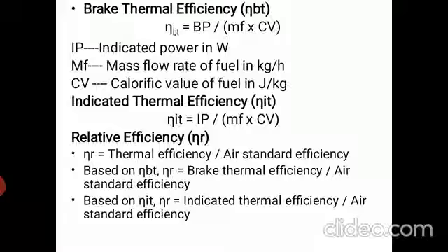Calorific value of any substance can be found from a bomb calorimeter. With the help of a bomb calorimeter we can easily find the calorific value of the fuel. Then the mass of fuel consumed can be found experimentally, either by weighted analysis or with the help of a burette.